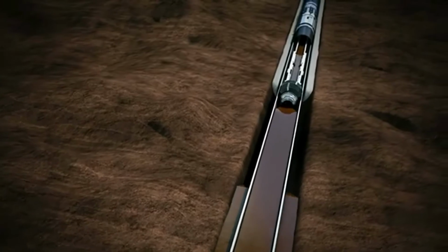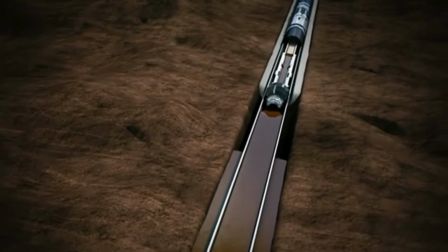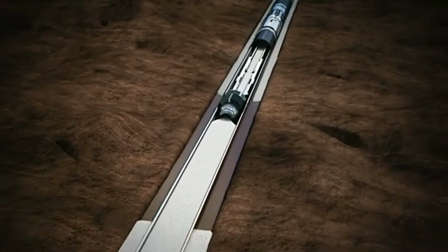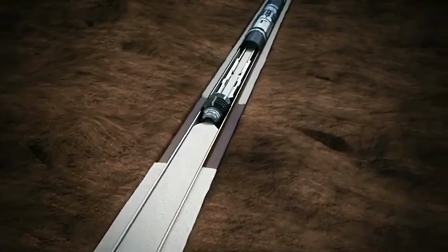upcoming cement job. Most wiper darts are compatible with the Blackhawk equipment. However, it must first be confirmed that the landing strings are wiper dart compatible as well. After mixing the cement, the wiper dart is launched from the cement manifold. As the wiper dart displaces the cement down the landing string, the pump rate will be slowed down by 10 barrels prior to hitting the Blackhawk diverter sub.